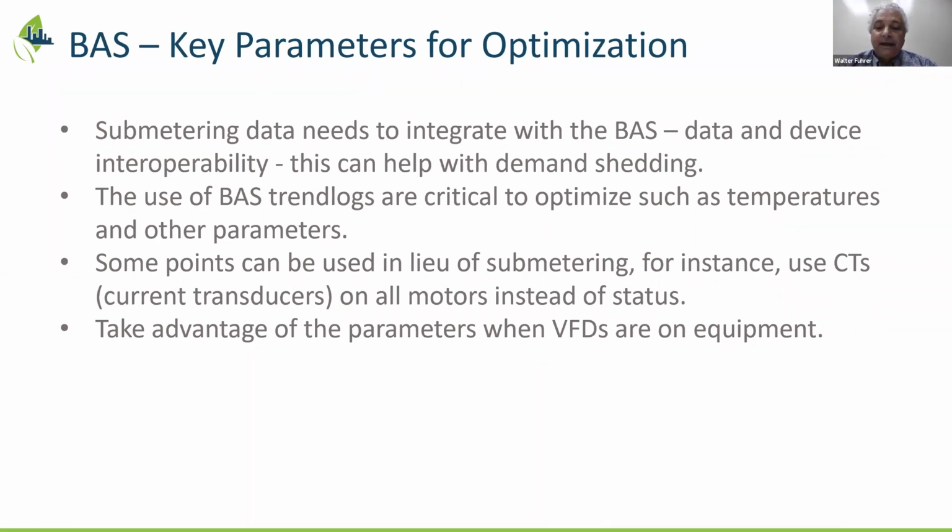Yes, Frank, we are. And you were correct. They were originally used more for a status on/off. And now more and more we're seeing that you can actually measure current with them. For example, is the fan running? Isn't it running? And also you need a virtual meter to see the power consumed. Now, when you use a CT in this way, it's not an exact calculation, but over time you can establish benchmarks and reference points quite simply by doing this. So if it's not a critical application, but you want to know what power is being used, it's a very cost-effective way to do it.